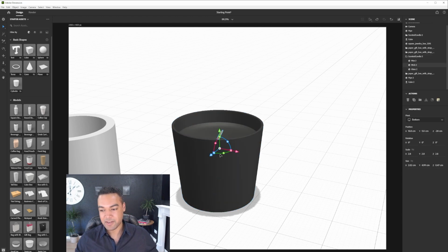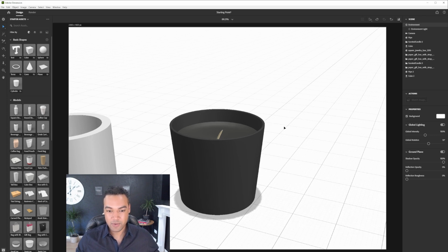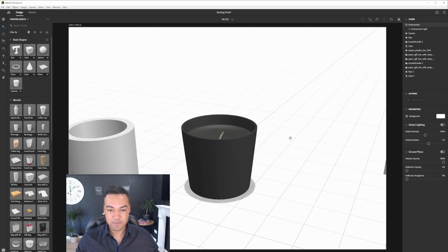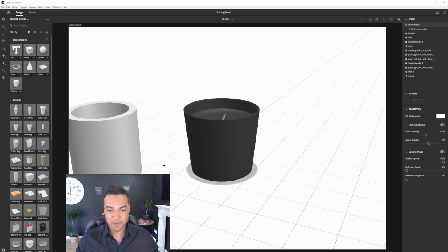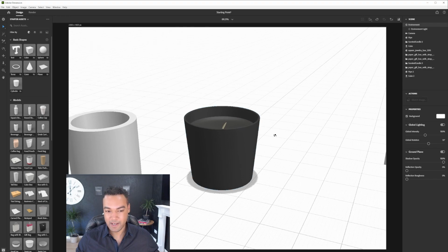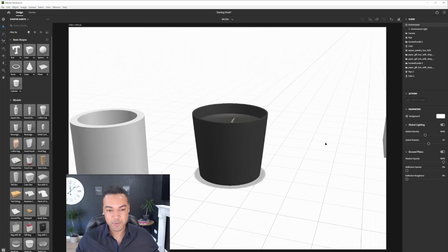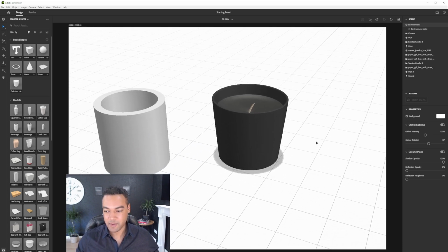And we'll look in the next class at changing the materials and the colors of these assets. Another set of tools you'll need to get around this software are the camera tools. So your mouse wheel allows you to zoom in and out. Holding spacebar and then right clicking and dragging allows you to pan around the canvas, and simply right clicking and dragging allows you to orbit the camera. So using those simple tools, the software is really intuitive. You can probably dive straight into it and start using it just given those few techniques.